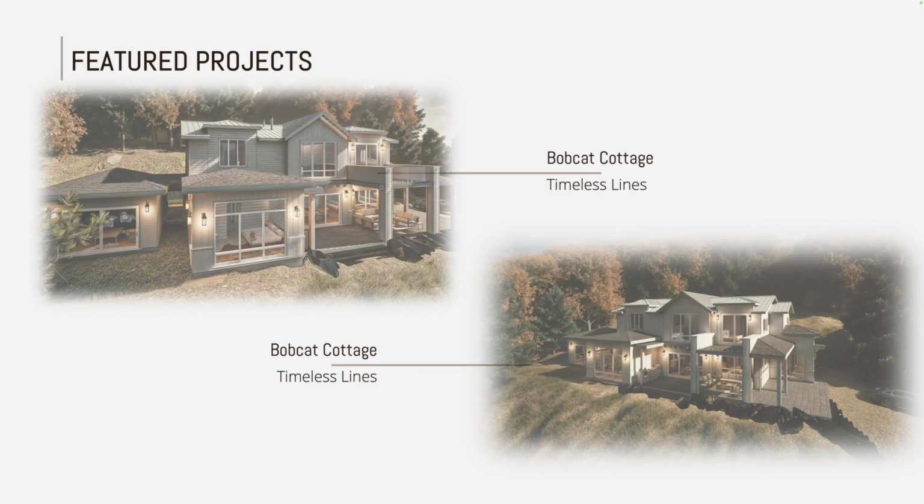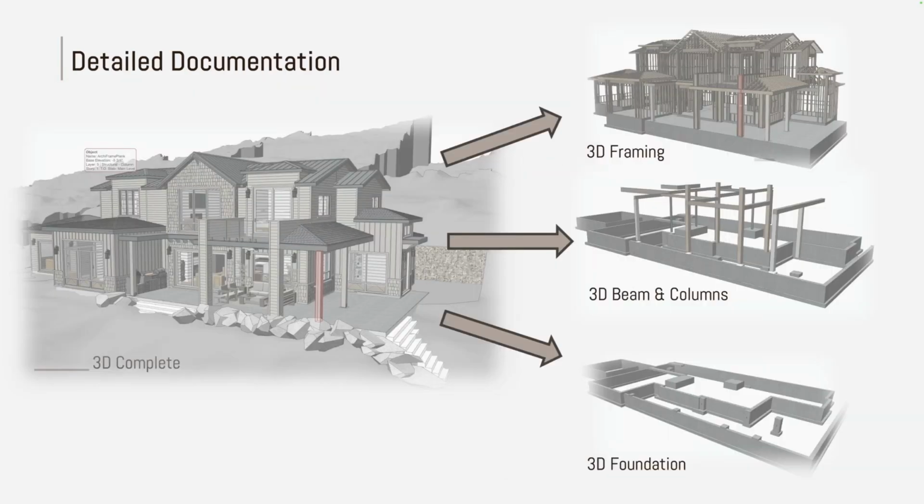And in terms of trying to get the construction aspect across to the contractor, the cut list and ArchiFrame really help sort of dial in a project such as this. You can kind of see here how I've been able to leverage ArchiFrame and Archicad to create layer properties and 3D documentation, sort of separate out foundations, beams and columns, wall framing, trusses, so that those layer combinations can be output and then imported into something like BIMx, so the contractor can see everything I see.